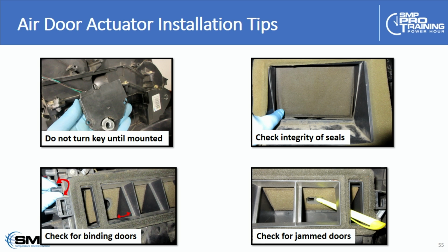I referenced this a little bit previously: the foam seals and rubber seals on the air doors themselves and inside the case, generally on the blower motor, the HVAC, the heater core and the evaporator core. It's very important that you've got good airflow integrity inside the HVAC case.